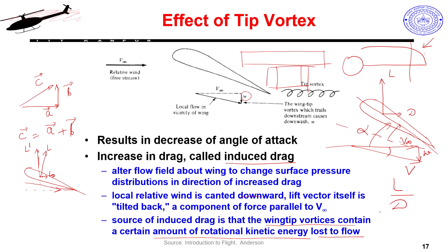If you look at Cessna's L by D, so we are now talking about lift to drag ratio, and this is the key determining factor for my performance most of the time. Another parameter will also come in, we will come to that later, but this is the most defining parameter which governs my design all the time. The moment you look at a UAV, you would want to know what is the L by D of this. If it has good L by D, you can assure that it will have good performance characteristics and is going to give you the most optimal performance.